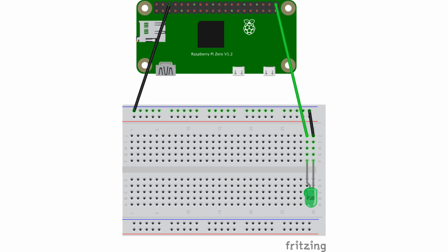And we're going to do the same thing here. So we are going to plug one end. If you have a green wire, we're going to plug one end of the green wire into GPIO port 21. I'll talk more about the ports in a moment. And the other end into J29. That's going to be your positive wire. Then that's going to travel through the breadboard, which I'll explain more later, to the LED.